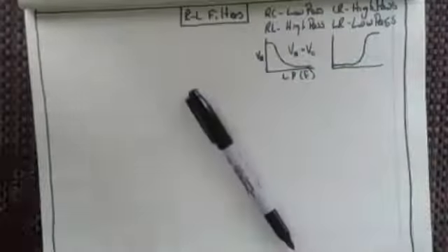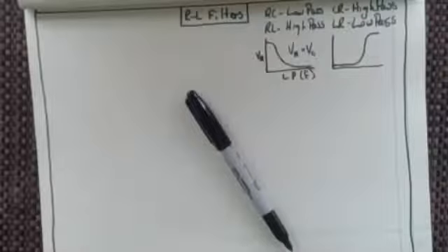Now, on the old style telephone, not your cell phone, although actually the instrumentation in a cell phone would do predominantly the same thing that your regular home phone had, and that was a limitation on the frequency bandwidth from 30 hertz up to about 3,300 hertz. And that was the bandwidth of a telephone communication system, or your home telephone communication system on the trunk line. And of course, what that did was it meant that really high frequency stuff could not be